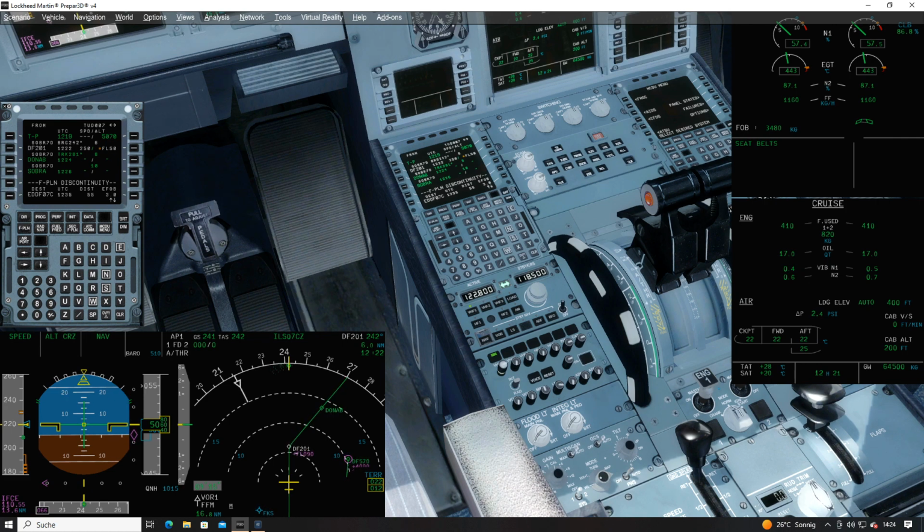So, we don't want to continue on the departure route. We want to join the final approach. On the one hand, we can either just turn by heading, but unfortunately, the departure route is still active. To have all the advantages of the aircraft, for example, if we are going around, having a missed approach and want to join the missed approach procedure, we have to have the correct waypoint sequencing.